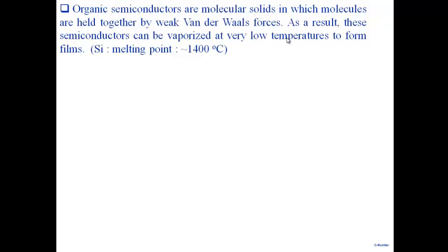And you do this evaporation, thermal evaporation for say half an hour or whatever, and then you form a nice film of organic semiconductor. And you can get a film which is 50 nanometer, 100 nanometer, 150 nanometer films. So the films that we talk about are very narrow. We are not talking about bulk crystals which are 300 micron. We are talking about this whole organic electronics. Another name for it could be thin film electronics. All the films that we form are all thin films. Okay, 100 nanometer typical dimension.